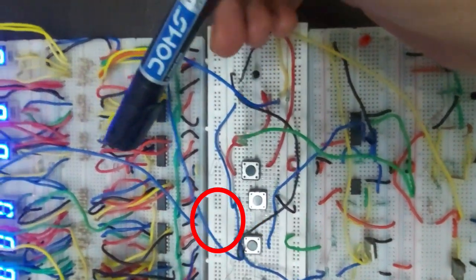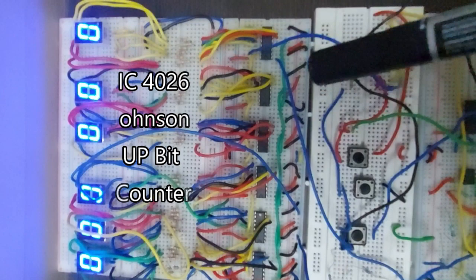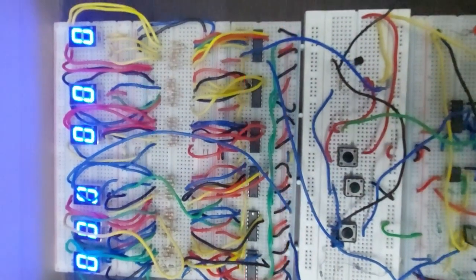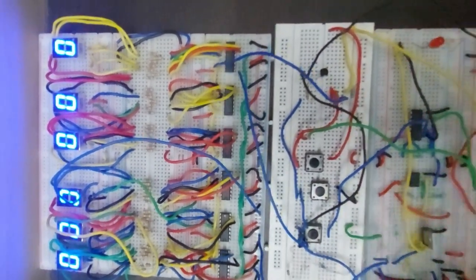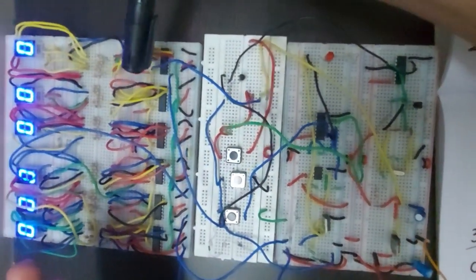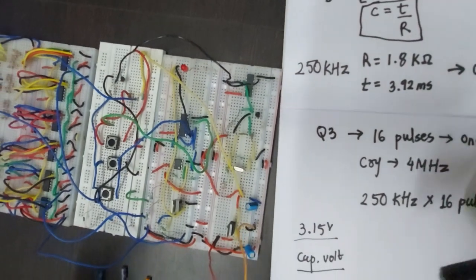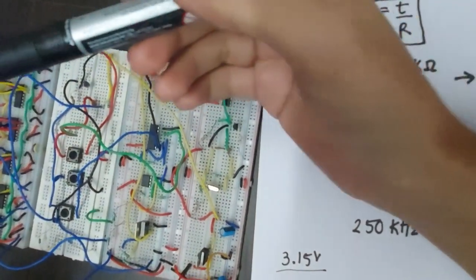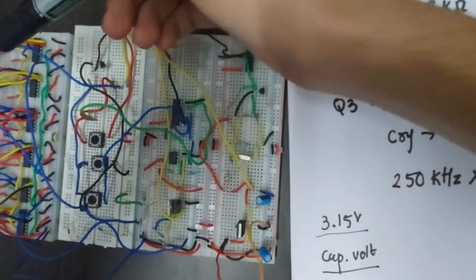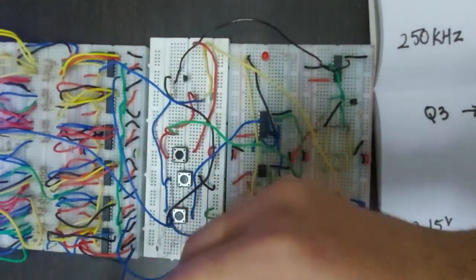For the counting circuit, we have used the 4026 Johnson counter IC, and we have used 6 such ICs. The 250 kilohertz frequency we have produced here goes to the first IC as a clock. The carry of the first IC goes to the clock of the second IC, and so on.